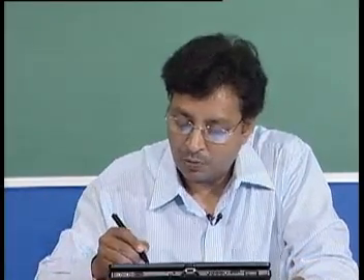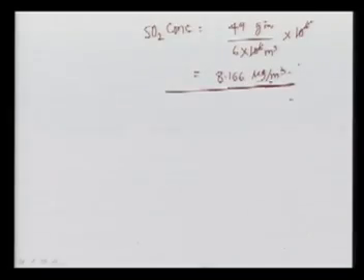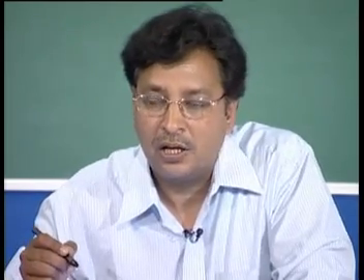So what we did is we found the overall SO2 concentration in the triangular area. But we have to remember that this meter cube is a function of temperature, and the temperature within the triangular prism is changing. So I must convert this to the required temperature where my standard is.